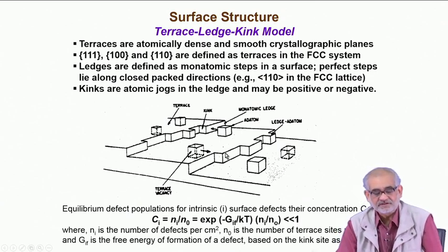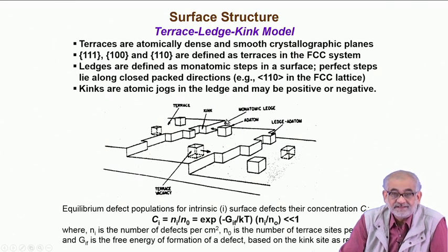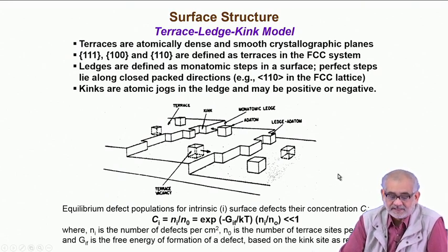Now, this again requires a much longer discussion, but the point I am trying to make is that if you are dealing with a metallic surface, then incorporation of an atom onto the growing solid-liquid or solid-vapor interface is much easier, and as a result a metallic crystal can take any shape. Whereas when you are dealing with ionic crystals with very high bond energy, the surface morphology will not be random, but will maintain certain preferences of orientation and geometry. And this is because the surface energies are vastly different between metallic and ionic crystals.